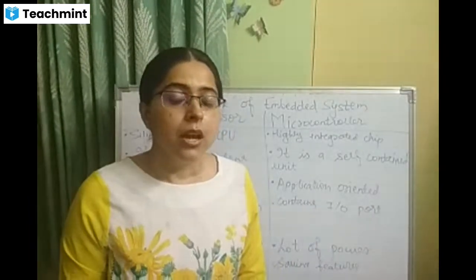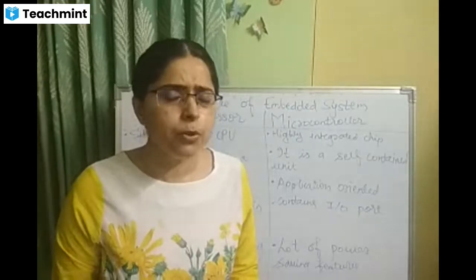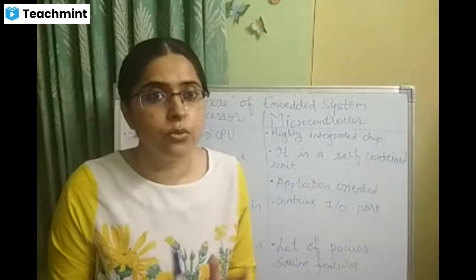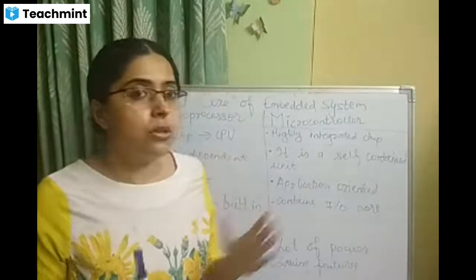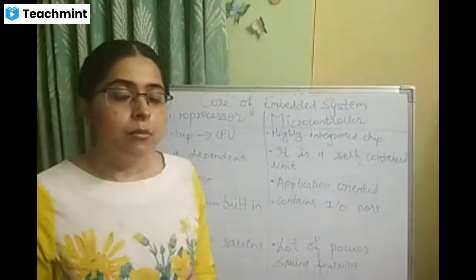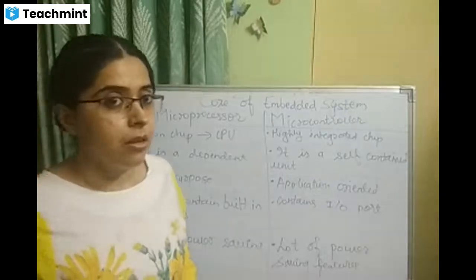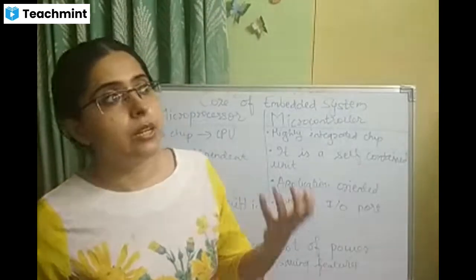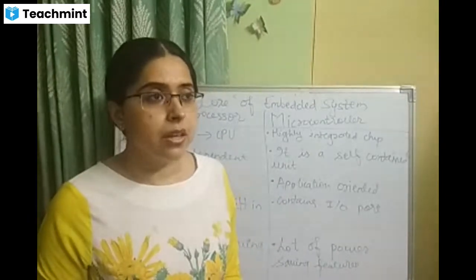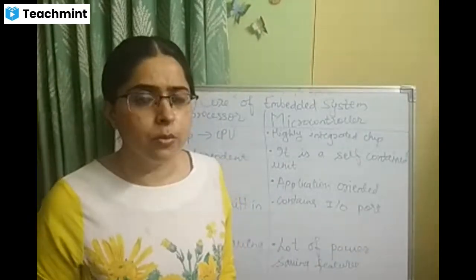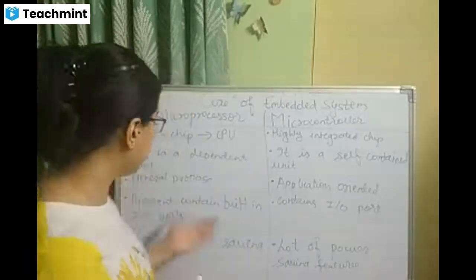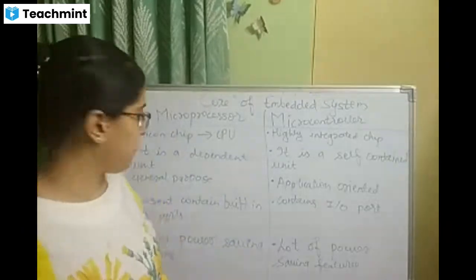Input-output ports are present, and you can use them as 8, 32, or 16-bit ports. There is no need to interface an 8255 with a microcontroller. The 8255 is used only for interfacing a microprocessor because the input-output ports are not present. For example, if you want to interface a stepper motor or any other memory chip to an 8085 microprocessor, you need an 8255 chip, because as I said, it doesn't contain I/O ports.